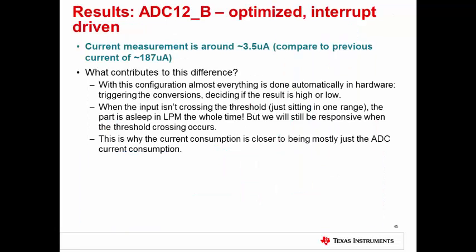The functionality of both examples is the same, but as you can see, these few changes allow the MSP430 to do more work in hardware. We can take more advantage of the MSP430 low power modes, and we have much better current consumption than with lab number 1.